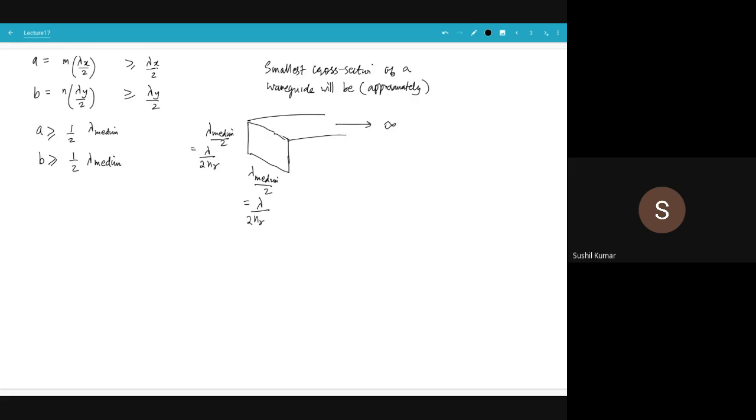I think they use 30 or 40 gigahertz, somewhere around that range. So 1 gigahertz is 30 centimeters, 10 gigahertz is 3 centimeters, 50 gigahertz would be divide by 3, so around 1 centimeter. Still, if you were dealing with frequencies around 30-40 gigahertz, you would still need centimeter sized components on there, which is not possible.